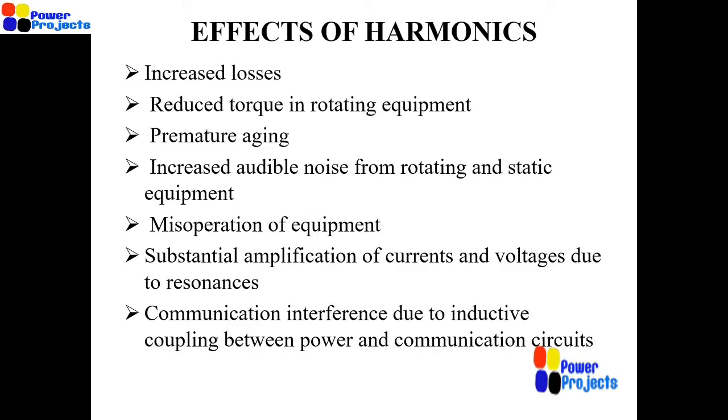Another slide. Here you can see some of the impacts or effects of harmonics, like increased losses and reduced torque in rotating equipment. Actually, harmonics can also introduce braking torque. If it is a second harmonic in nature, it causes premature aging, meaning the life of the equipment comes down. There is also increased audible noise from rotating and static equipment, maloperation of equipment such as relays, and the neutral current sums up if it is, let's say, zero sequence current. So that is the answer to Aman's question on why to reduce the harmonic distortion.